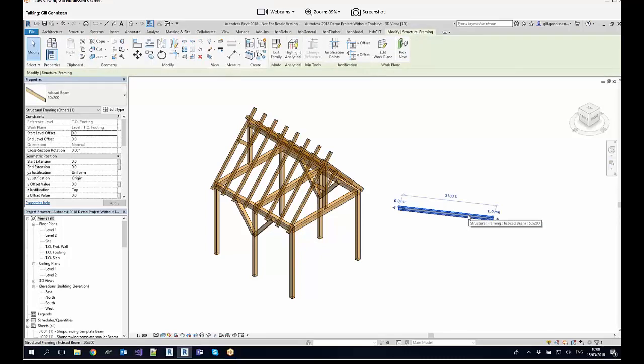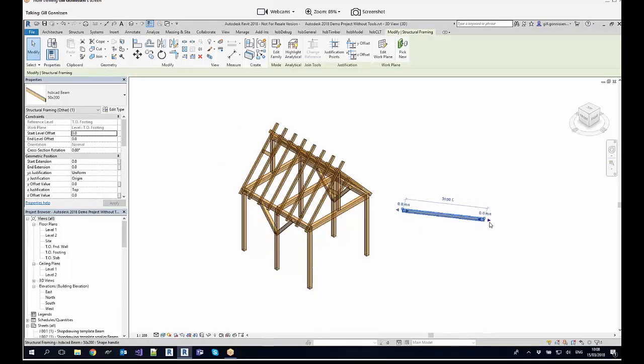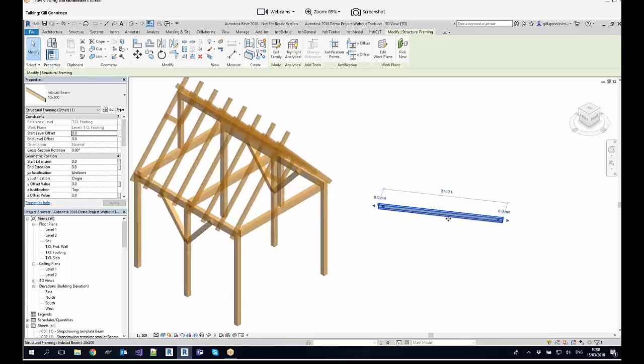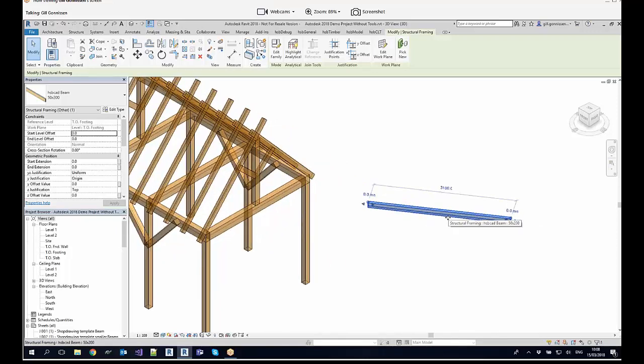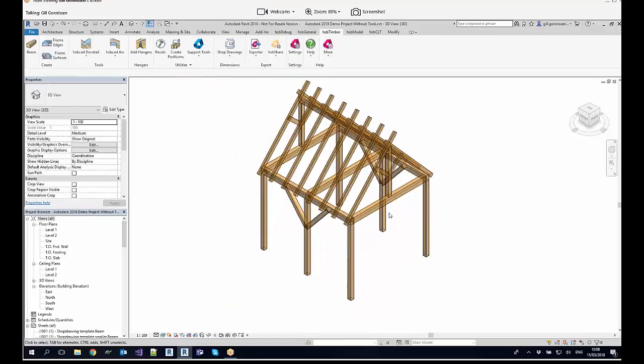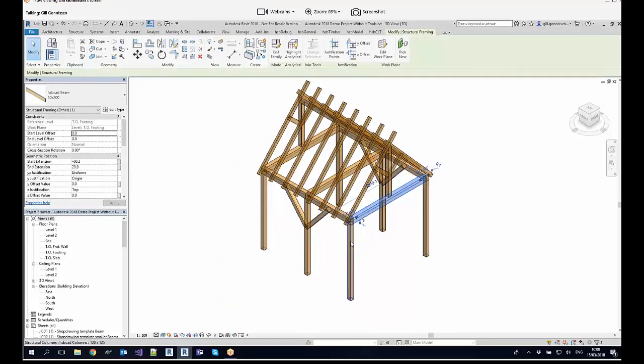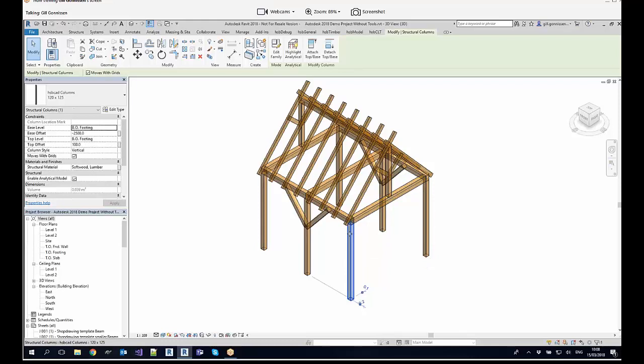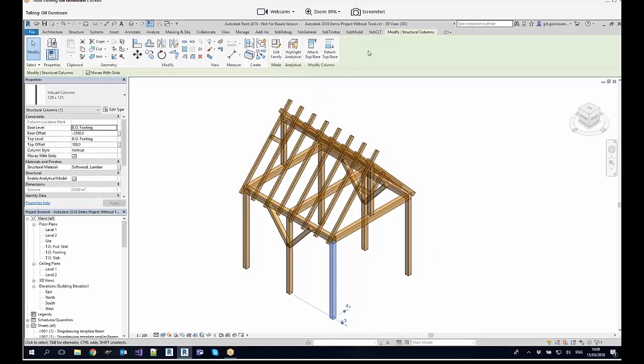So we try to use, with our version from Revit, only Revit functionality. That's very important, so that the user doesn't get strangled along with things that they don't understand at the moment. So I've completed a whole frame actually from those beams, and columns as well, to work with later.